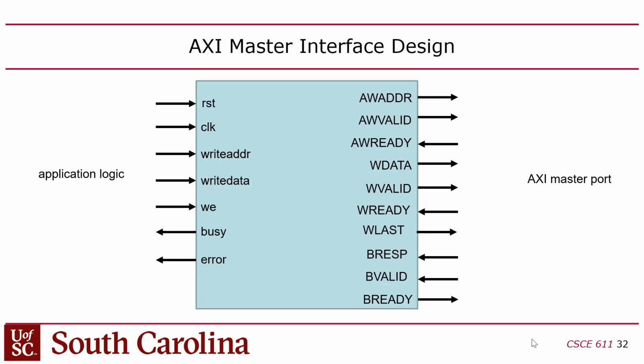Now this is actually quite common, because if you want to design a peripheral to connect to this bus, then you have to basically create the logic that will reconcile your application logic with the bus. It's like a bridge, right? You have to put a translator here that will translate your code in a simplistic interface, like a register file interface, into the AXI language, the AXI protocol, right?